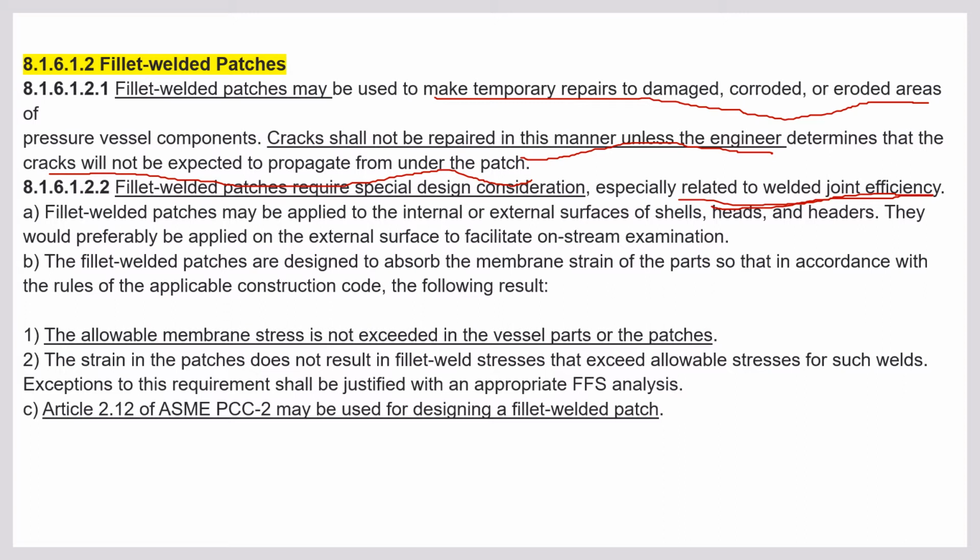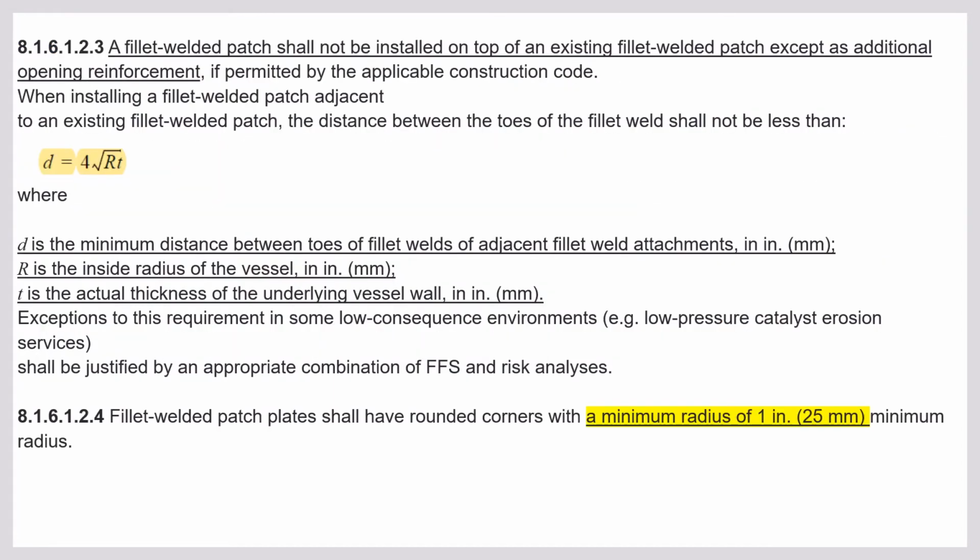Okay, so here fillet welded patch requires special design consideration, especially related to weld joint efficiency. Fillet weld patch may be applied on the internal or external surface of the shell, head and headers. They would preferably be applied on the external surface of the facility for on-stream examinations. Okay, the allowable membrane stress is not to be exceeded in the vessel parts and patches. These are some of the requirements you have to check for the fillet welded plates.